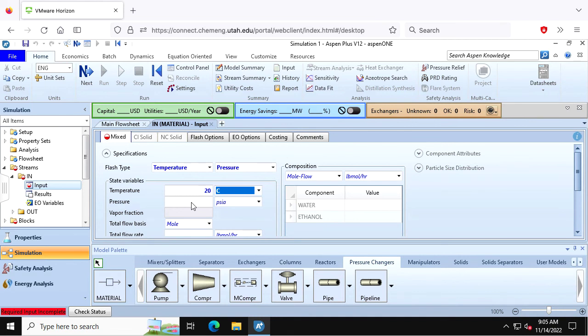How many inches of water per psi? Have you talked about inches of water at all as a pressure unit? No. We did a conversion once, and then it's like, this is wonky. It is, but you see it used all the time. And where you see inches of water used is in things like pressure gauges and differential pressure across orifice plates and things like that. There's a historical reason why they use inches of water. And an inch of water is actually a pressure unit. You would think it's a length unit, but it's like millimeters of mercury, right? You're familiar with that? So it's same thing, but now it's inches of water.